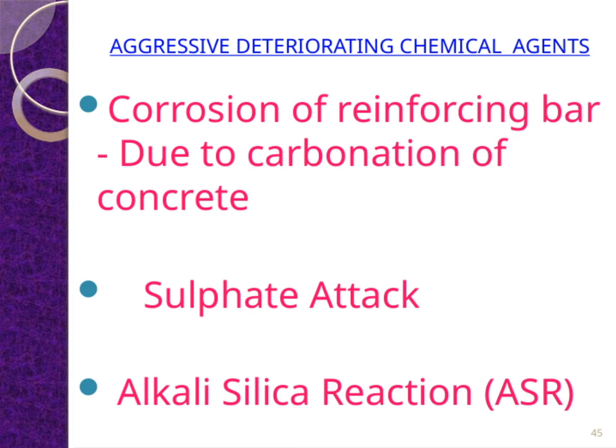We also need to consider alkali-silica reaction, or ASR. This occurs when reactive silica in the aggregate reacts with the alkali hydroxides in the cement paste, forming a gel that swells as it absorbs water. This swelling induces internal stresses, resulting in cracking and overall deterioration. All of these issues are caused by aggressive, deteriorating chemical agents that attack the concrete and reinforcement. Recognizing these agents and understanding their effects is crucial for designing durable structures and implementing appropriate protective measures. This way, we can extend the lifespan and safety of our infrastructure.